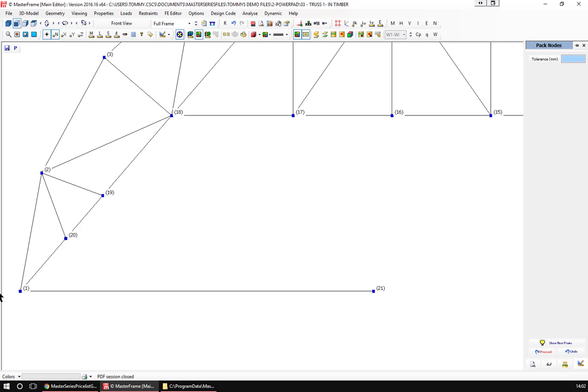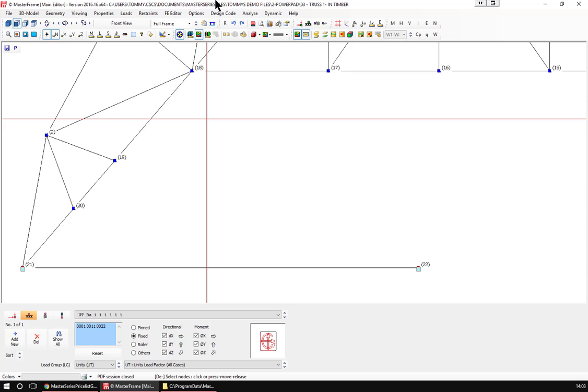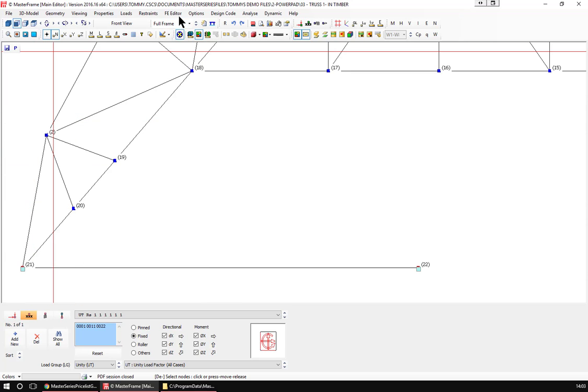So yes, it is done automatically, but that is also done as we try to export. So if I did an undo, I've got 2 nodes there. I go to restraints, nodal. I'm going to put a wee static support under this one of some sort. And now I go to analyze.